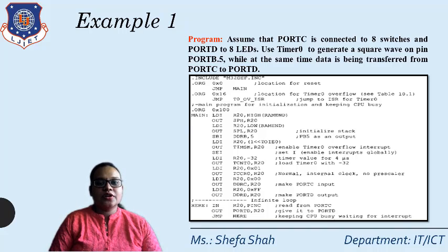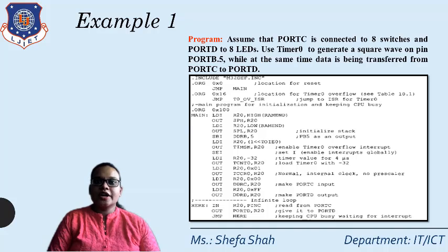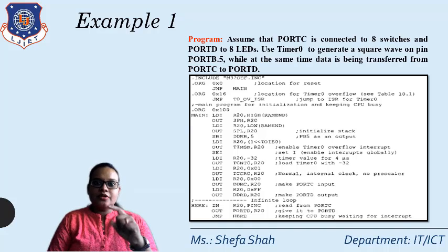While executing an interrupt, we make use of the addresses in the interrupt vector table. As we discussed in the steps for executing an interrupt, whenever the interrupt is called, it goes into the interrupt vector table where the address is found, and then it jumps to that address where the interrupt service routine has been written.